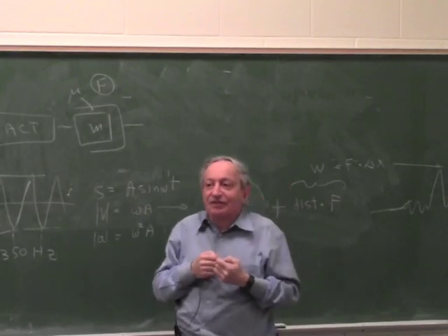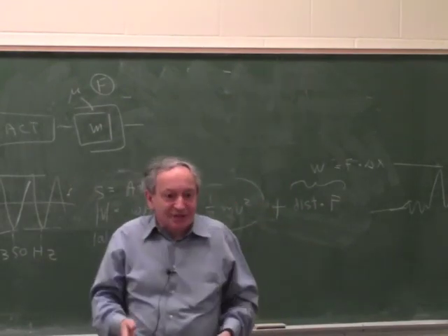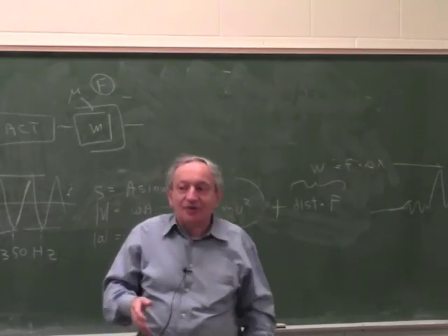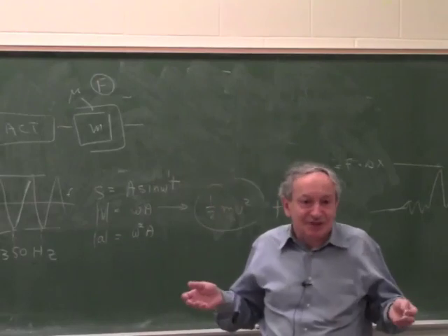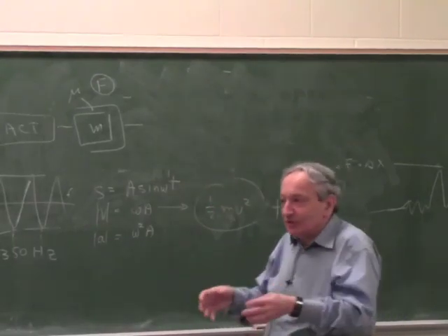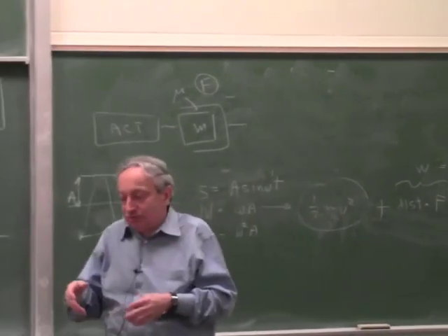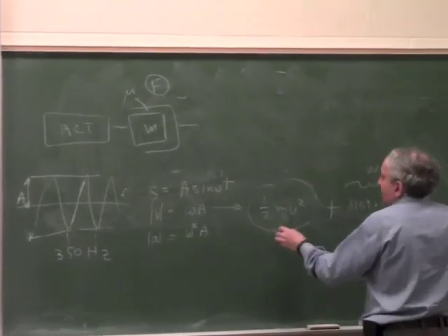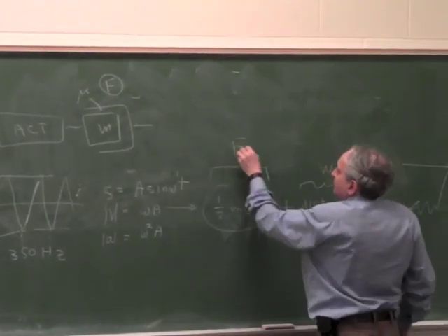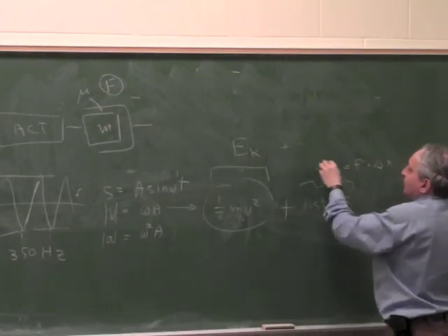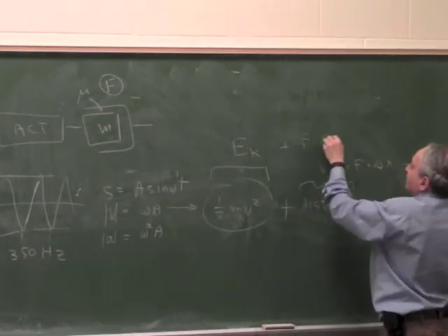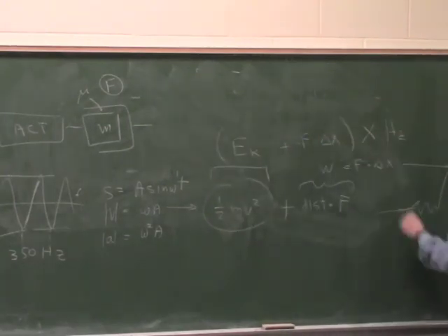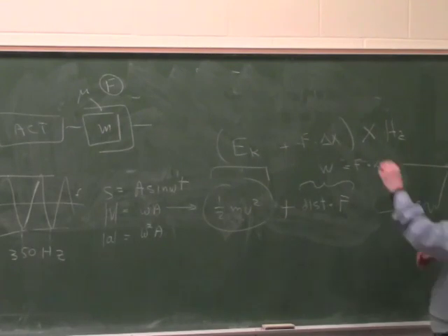Say gravity. Let's say you have a servo which controls an elevator. It lifts it against gravity with a force F. In theory it's all recoverable. But if you don't have regenerative systems, even that is not recoverable. So for small servos, like a machine tool, a disk drive, no energy is recovered. So per cycle, you have the kinetic energy, plus you have the dissipation, you have F times delta x, and all this is times the frequency, because this is per cycle.